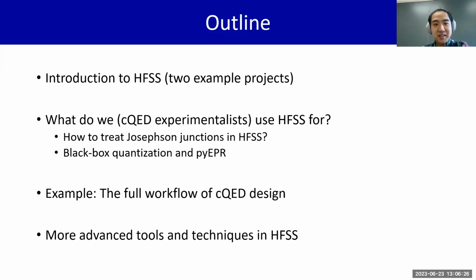Okay, sorry guys. So with the introduction to HFSS, we're going to answer a question: what do we, as circuit QED experimentalists, ask from HFSS? Is there anything specific we do with HFSS that is different from the classical microwave engineer? In particular, that is how to deal with the Josephson junction in such simulations, a trick called black box quantization, and a Python package called PyEPR. These are going to be mostly on the slides.